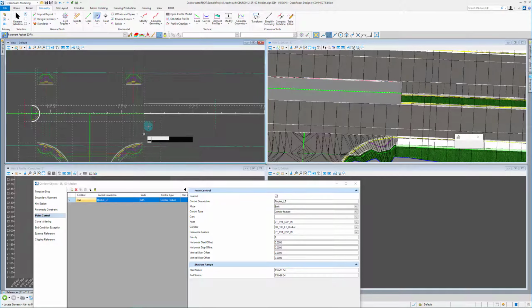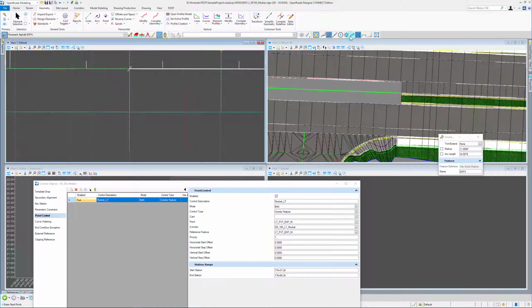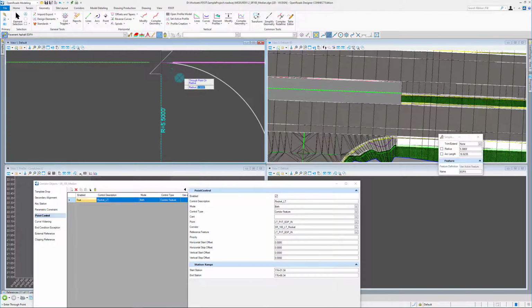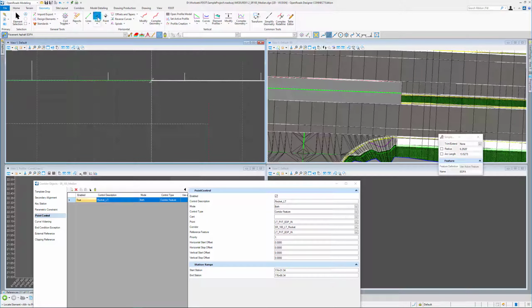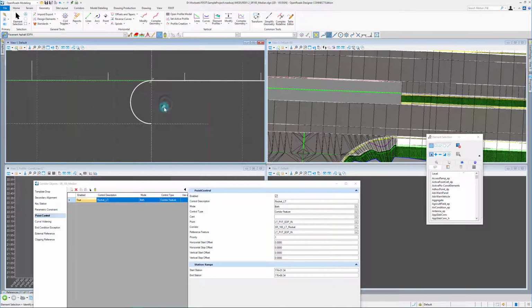Get our arc out here, and since I've already drawn this, I can pretty much just snap. See, I'm running into the issue of the arc. It doesn't want to. Sometimes we can alt. Yeah. So what I'm going to have to do is draw it from the other direction. So I'll draw it from here, snap, come down here. So that's basically how you fix that if you run into an issue where you can't get it to go the right direction.